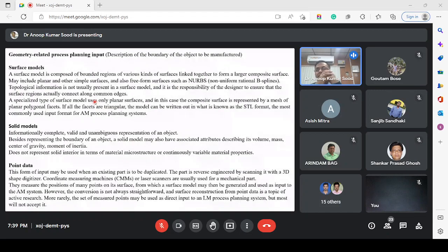An airtight or watertight model means that if I assume that I am filling this surface model, the mathematical description of an object represented with surfaces, with some air or water, because of the presence of this minute hole, which we call a puncture, there will be a leakage, and I will not get a single volume. That means I will not get a single unit. There will be some gaps in there. And if I build this object with additive manufacturing, for each layer I need a closed profile. Because of this gap at a particular location, I may not get a closed profile at a particular layer.